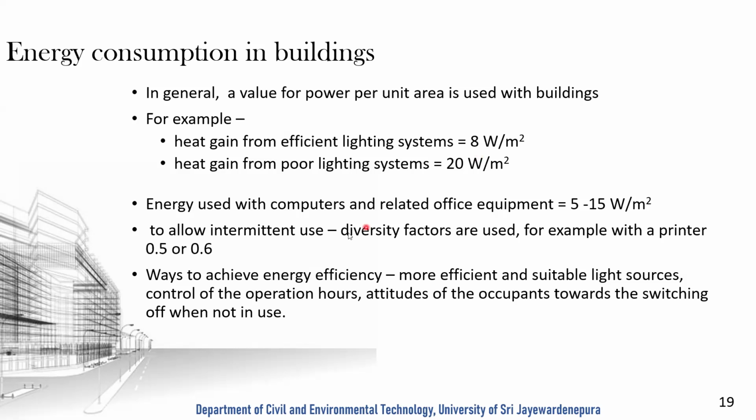Then for computers, like if you have an IT office where you have a set of computers, a good figure might be 5 to 15 watts per square meter. Okay. There's another thing I would like to discuss here: intermittent use. This will be important for your assignment as well.